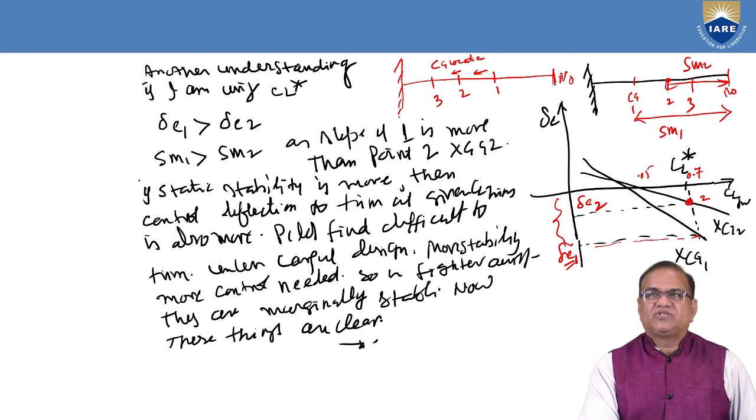As a designer, we should not make any attempt to have the aircraft center of gravity go behind the neutral point. However, for maneuvering cases and for high speed aircraft, fighter aircraft, it is recommended to have the CG very near to it, or a very small amount aft, so that maneuvering is very simple and takes less Cm delta E. Very little control power is required.